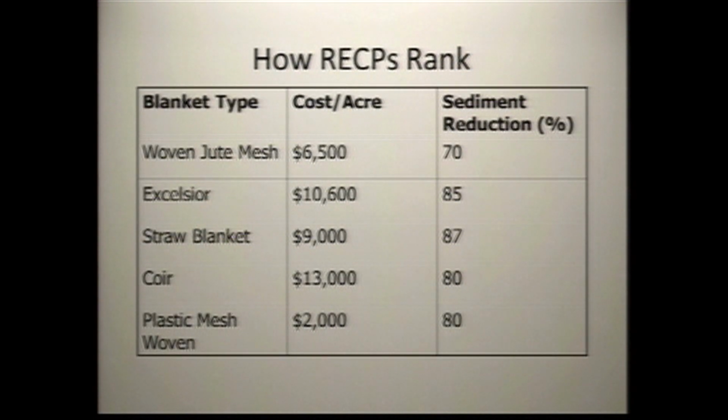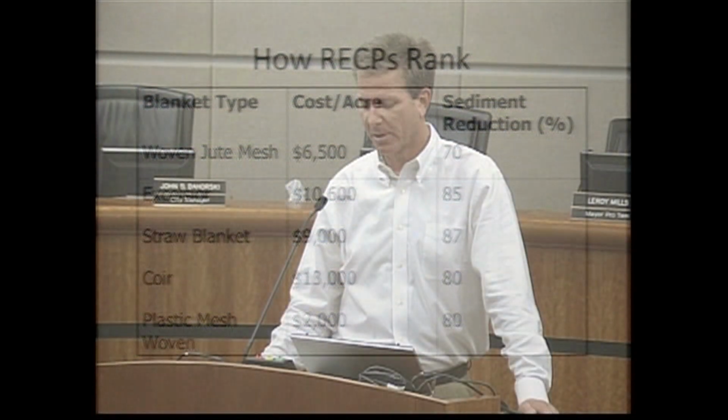And then the rolled erosion control products. There's a variety of those. We don't use the lower one there, the plastic mesh, anymore. Fish and Wildlife hates that. They don't want anything that's not biodegradable. But most of the rest of them, you really can't buy many of those anymore. The market shifts rapidly based on the regulation. But again, you can use a rolled erosion control product to stabilize an area that's not going to be seeded ever, but you need to get notice of termination filing.